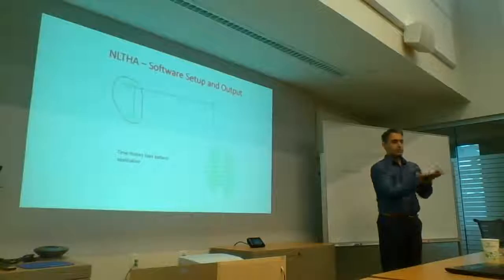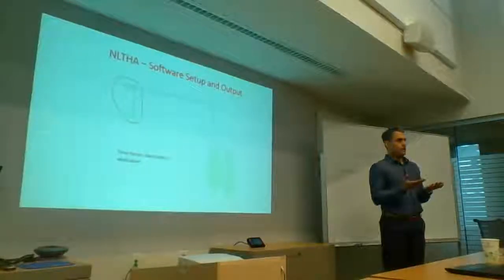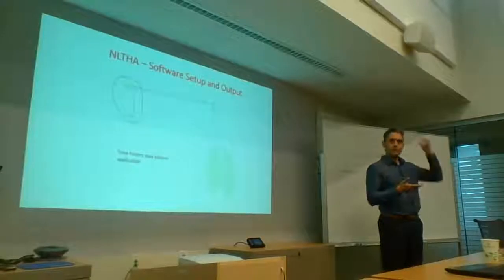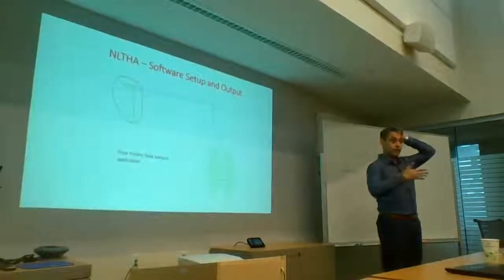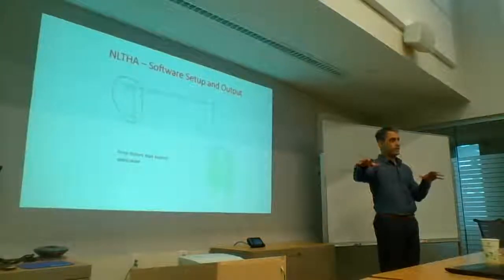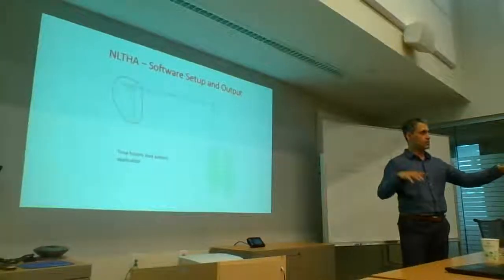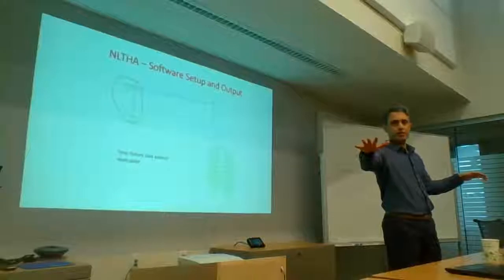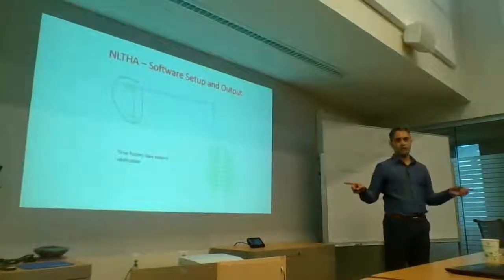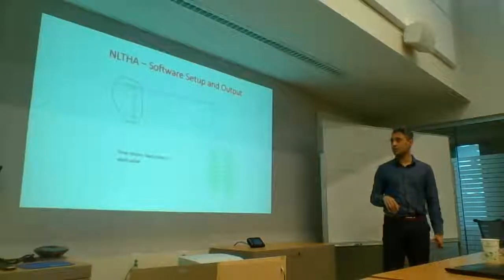And in a lot of the softwares, you can apply acceleration time histories, but when you apply the acceleration time histories, it applies those to every support location. So you can't have multiple support excitation. You can't put one time history here and a different time history there. If you want to do that, you've got to apply a displacement time history. That's certainly the case for CSI bridge.